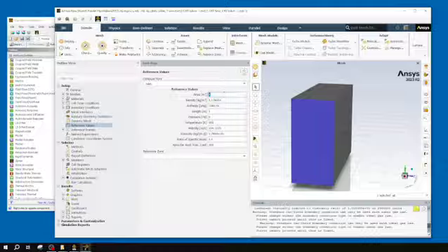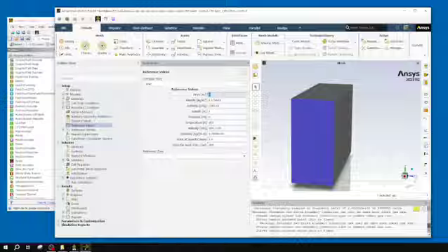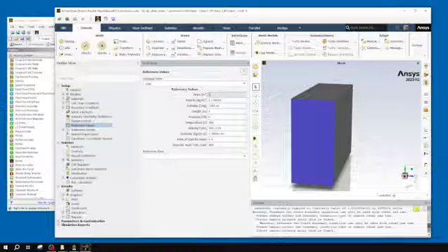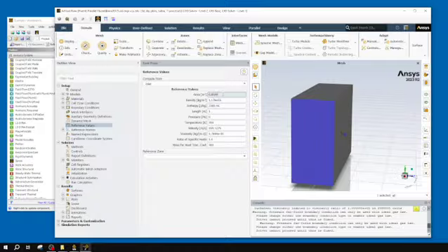There it is. So for the wing I imported, it is 0.839555. So that is important to put in as we have Fluent calculate our coefficient of lift and coefficient of drag for us.